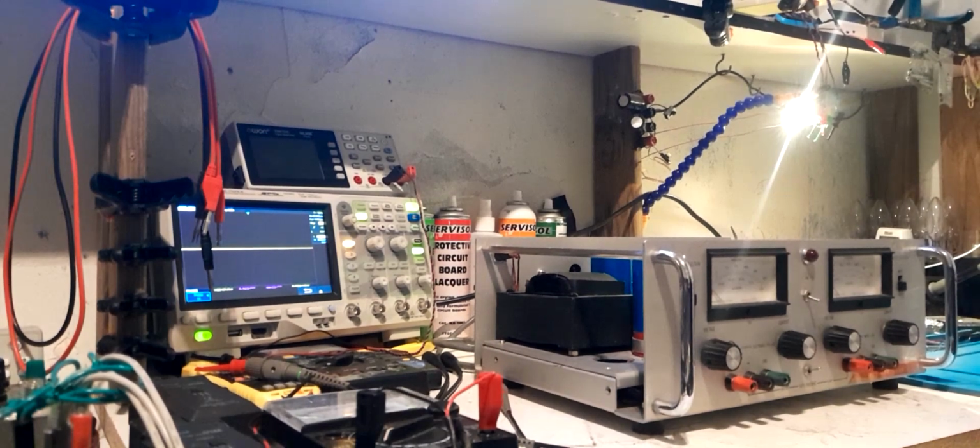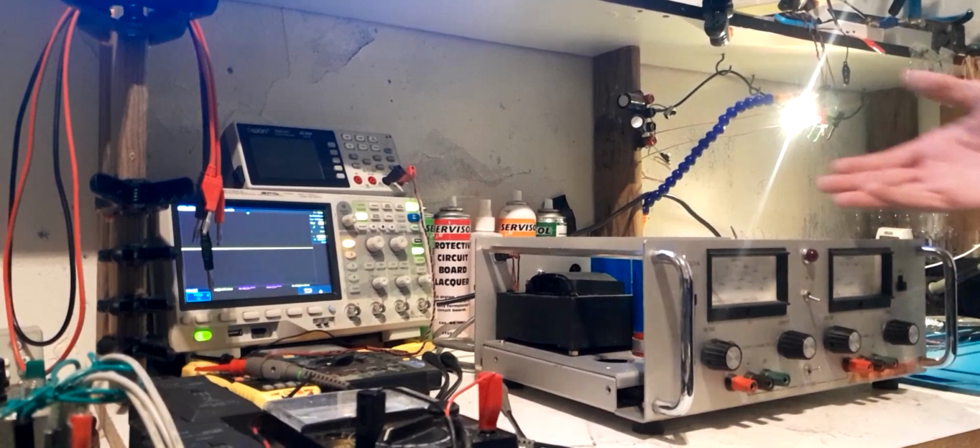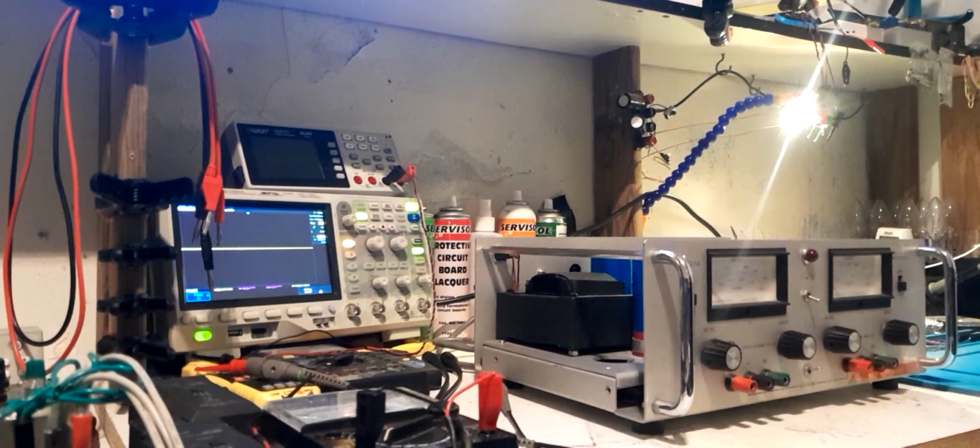I don't know that would be the best idea. I already put some in there, but I put them in there with bigger electrolytics at the same time, and that made things worse. But I honestly think it was the 1 microfarads that made things worse. So I'm probably going to put 0.1s in there because, you know, low ESR electrolytics and 0.1s versus non-low ESR electrolytics and 10 nanofarads. So I don't know if you get my thinking there, but it's how we do things now.